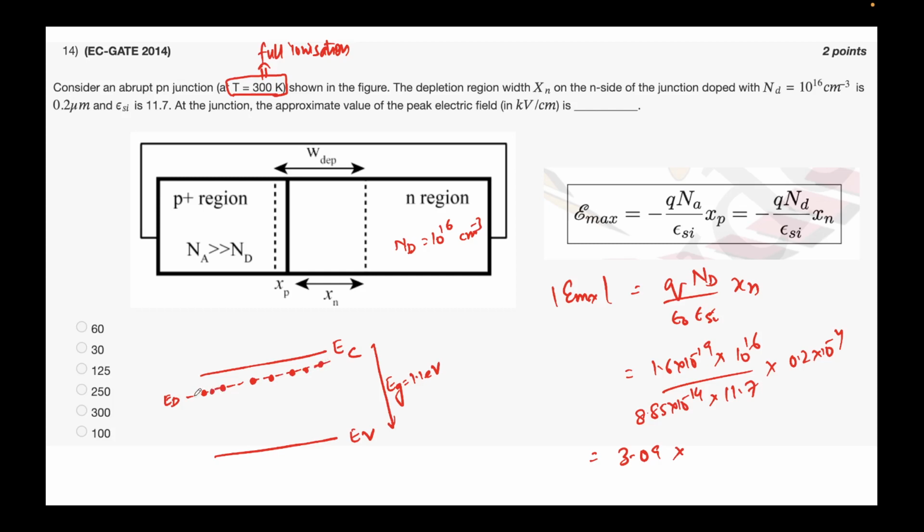Just below the conduction band energy sits the phosphorus level. You remember phosphorus is pentavalent, but in order to fit into the silicon lattice, which is bonded with 4 because silicon has a valency of 4, the phosphorus forms 4 bonds and an extra electron can be free. That extra electron at room temperature requires very small energy. At room temperature, the energy kT by q, 26 milli electron volts, is sufficient to excite a lot of these electrons into the conduction band.